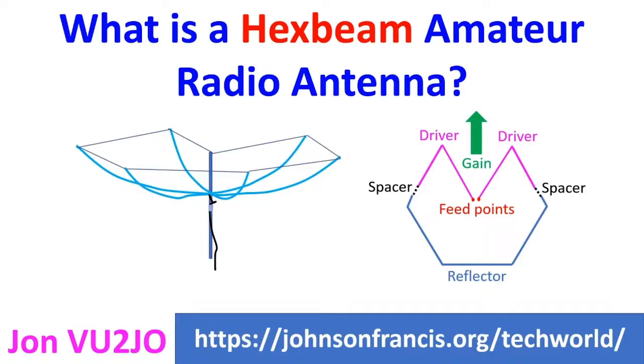Lesser size would mean a lightweight antenna with obvious advantages on the mast and rotating infrastructure, avoiding the need for a hefty antenna tower. Multi-band Hexbeam antennas covering multiple bands like 20, 15 and 10 or more are popular. In multi-band Hexbeam, the elements for the lowest frequency are at the exterior of the antenna. Vertical spacing between the elements is critical as multi-band elements can influence each other if the elements are not parallel.